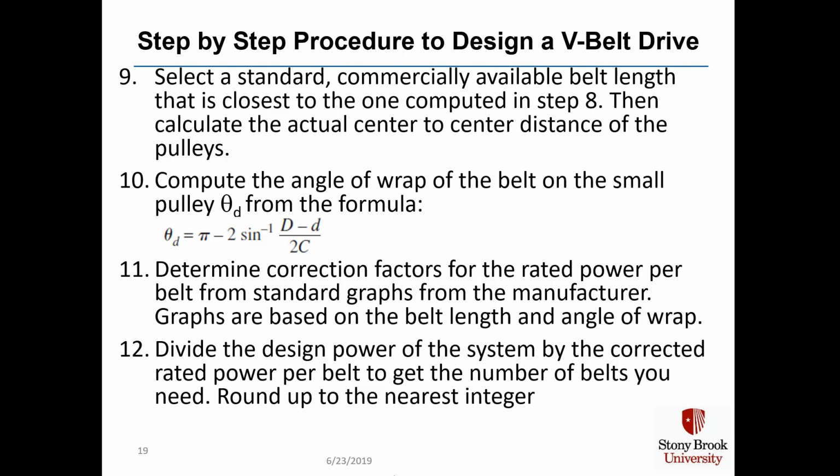This number is usually a decimal number, but recall that belts only can be purchased and used in integers, so you always round up to the nearest integer for the number of belts to use in your system.